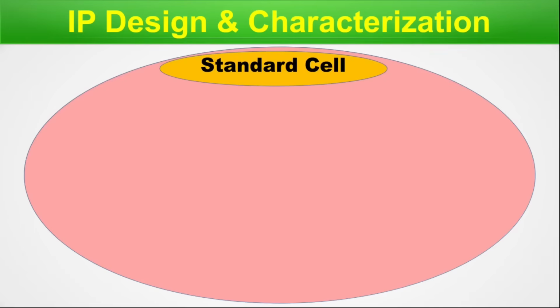The standard cell IPs are the most widely used IPs. Why? Because these are the heart of any digital design like ASIC or SoC design. Also, most of the time, the characterization jobs are for standard cell characterization. Generally, the standard cell IP library contains a huge number of total cells. Here, I would like to mention that each design block is called a cell in any part of the IP design. Now, the standard cells have a collection of unit logic cells, sequential cells, combinational cells, power management cells, and special types of cells like filler cells, decap cells, A2D, D2A cells, and ECO cells, etc.